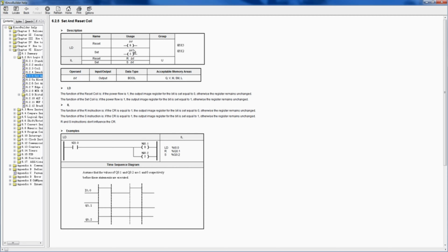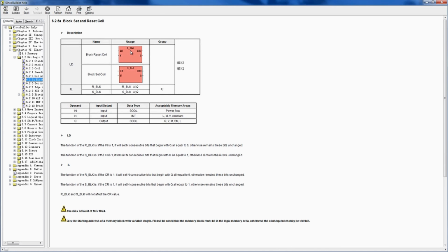Then press that and it would start, and press another one that would end it. That way you don't have to have a push and pull switch to start and stop and kill operation. And that same thing you can do block resets. That would be anything that is back to back. So if you want to reset Q 0.1, 0.2, 0.3, or you want to set M 1.1, 1.2, then you can use these block resets, but they have to be consecutive.